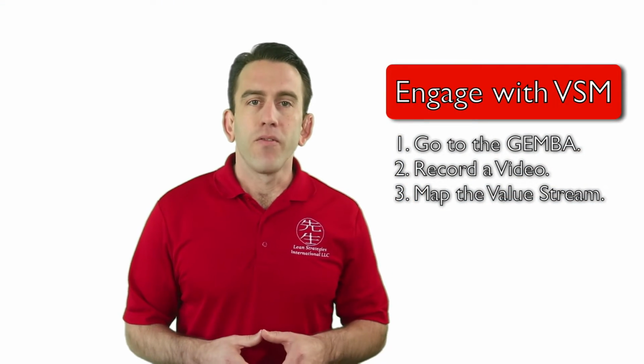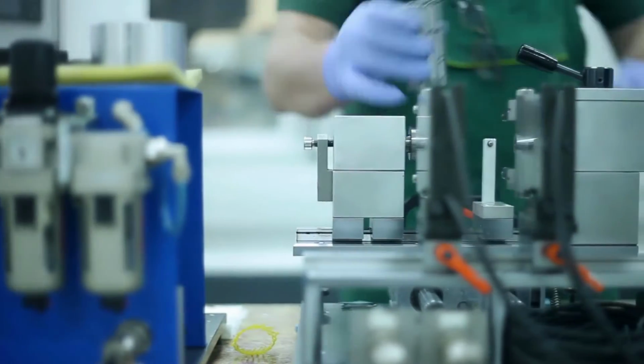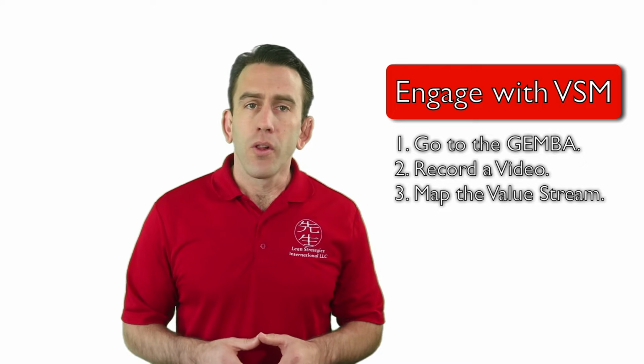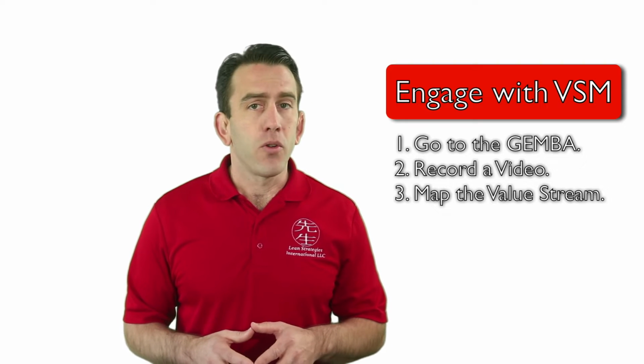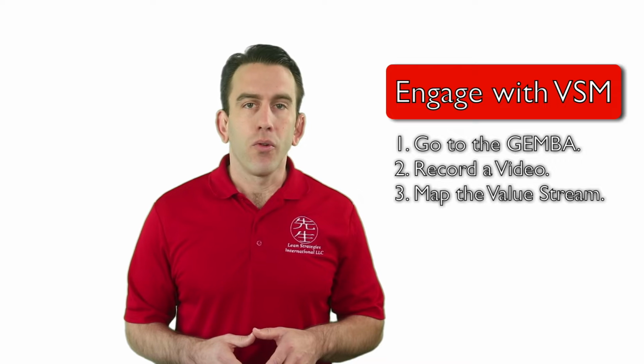You'll want to capture video that really focuses on forms of waste like hand and body movements, transportation waste, motion waste, and overprocessing. The video can be shown to the person or the team that completed the actual setup. Then they can help you to find opportunities. The last technique is to map the value stream.